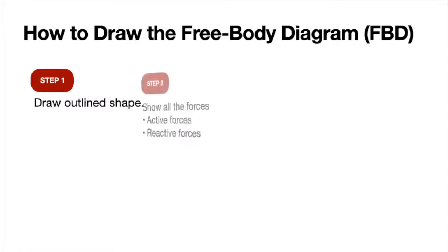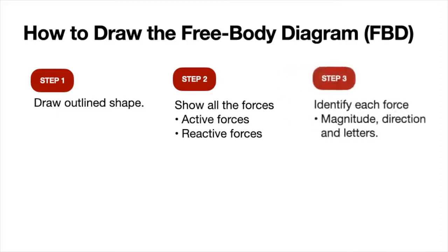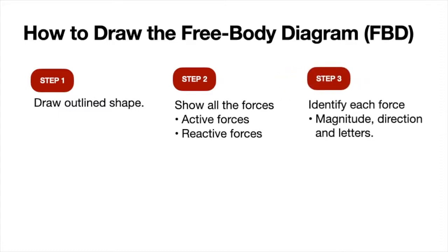And then the second step is to draw all the forces subjected to the shape, whether it is an active force, an external force, or a reactive force or internal force. Okay, and then all the directions of the forces and magnitudes should be identified and labeled accordingly.